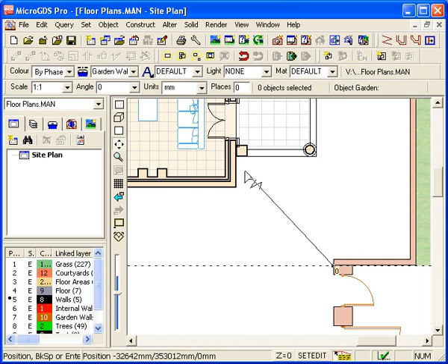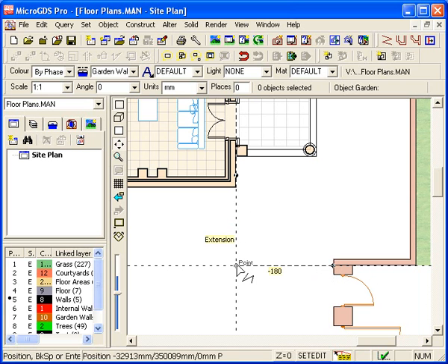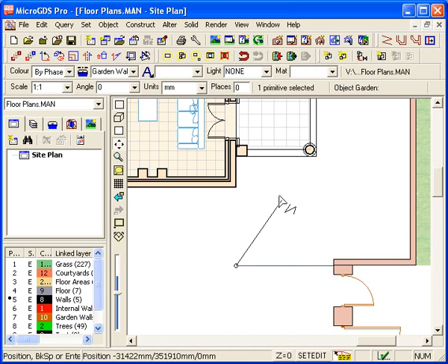Now, I want to align with this wall. Hovering over the wall created a vertical guideline. Notice this time the vertical line displays the label extension, indicating that the construction line has extended from the wall edge. All I have to do now is slide my mouse down to where the two guidelines would intersect and click a point snap, and one final point snap to finish the line.